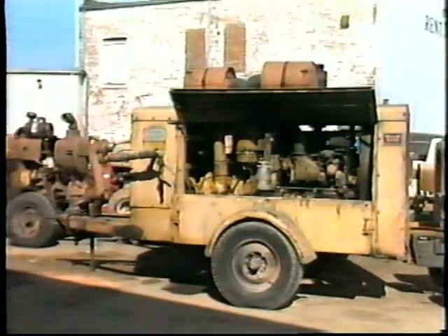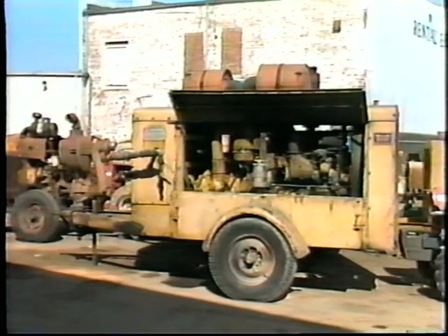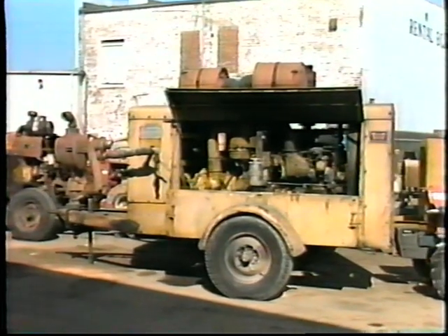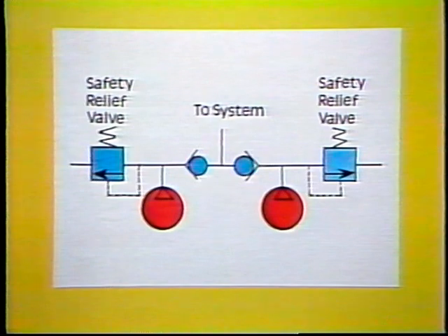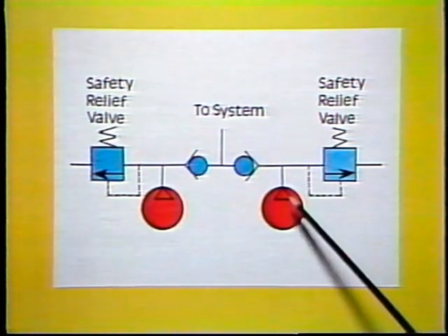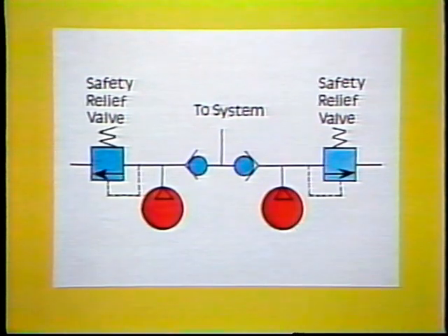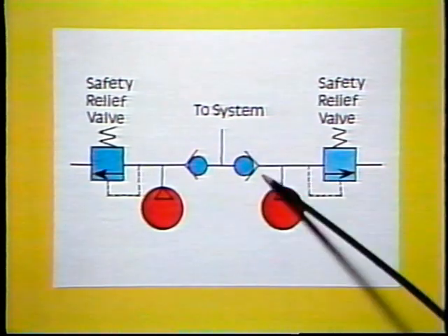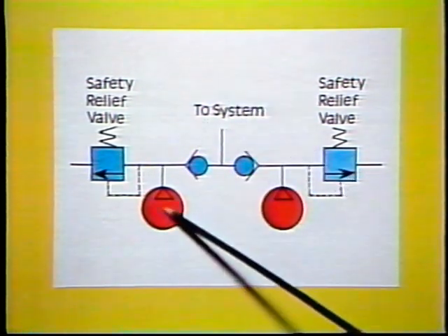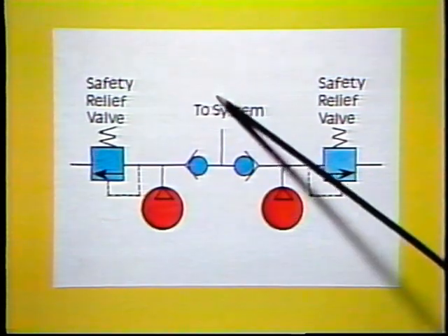You'll probably want to have standby capacity for emergency situations, and often this can be accomplished with the addition of external piping so a mobile unit can be connected. One reason for considering more than a single compressor is that with 2 or more compressors supplying a system, you'll have some backup capability in case one fails or is shut down for maintenance.